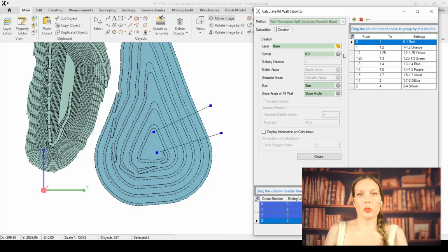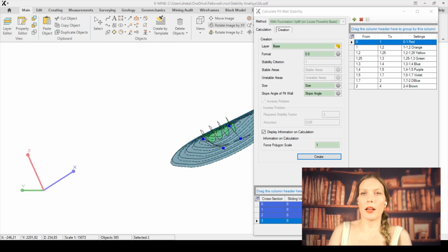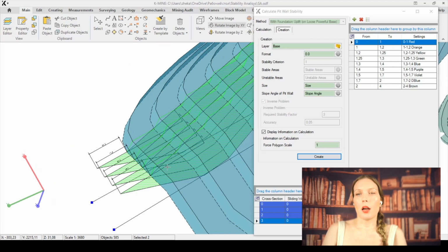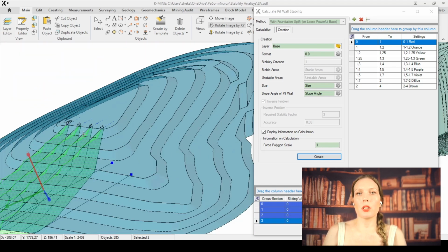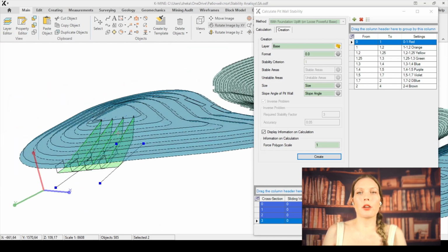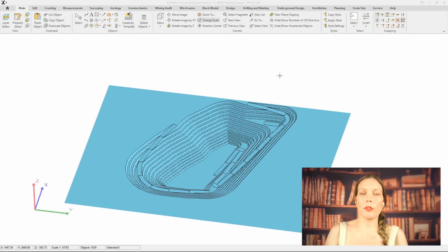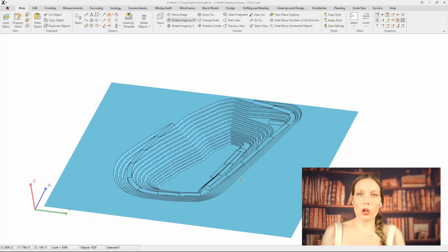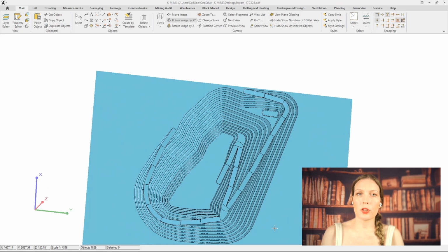And K-mine can automatically iterate through multiple possible slip surfaces to find the most critical one with the lowest safety factor. And this dramatically simplifies the engineer's tasks, enabling rapid analysis of complex slopes, which include multiple soil layers and water conditions.